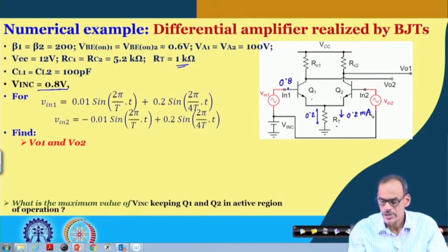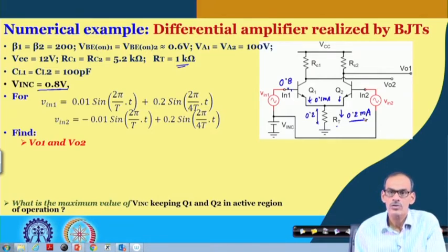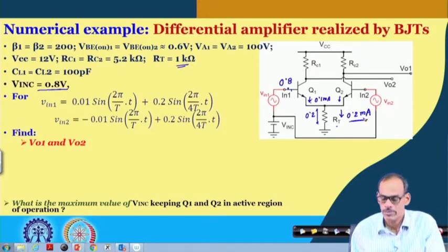Of course, strictly speaking, if we have 0.2 milliampere current and a split of this current, and the emitter current is say 0.1 milliampere, then VBE will not remain at 0.6, it may be definitely lower than 0.6, maybe around 0.5. But even if it is 0.5, the value of this current is quite low compared to our previous case, where we considered the current to be 1 milliampere.